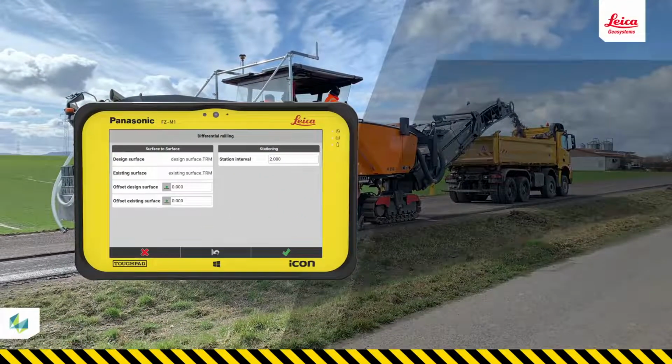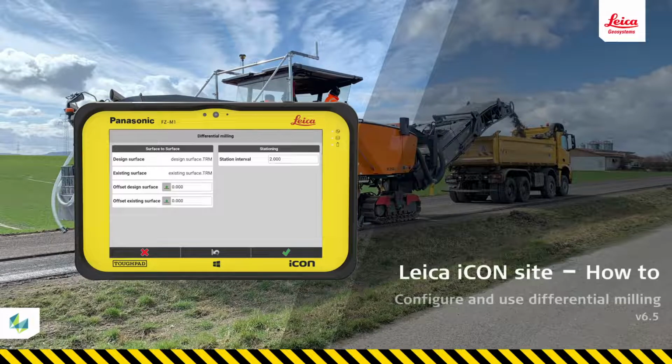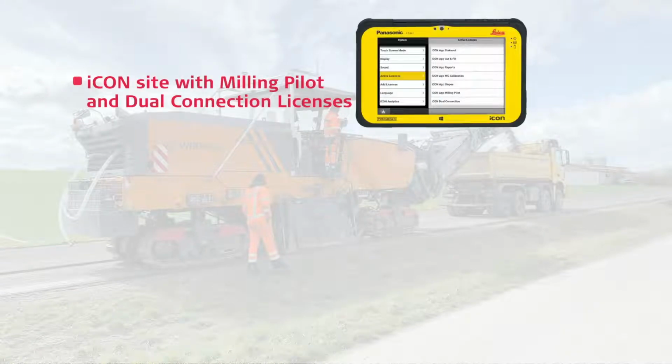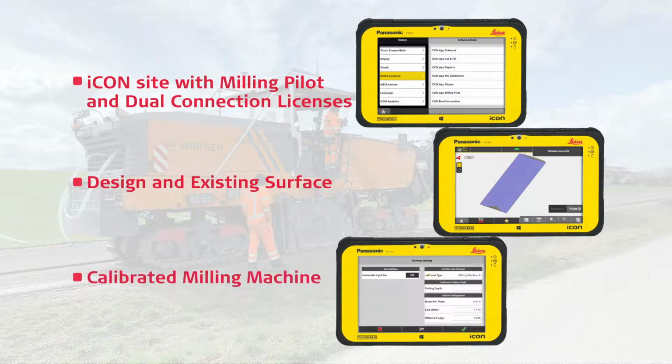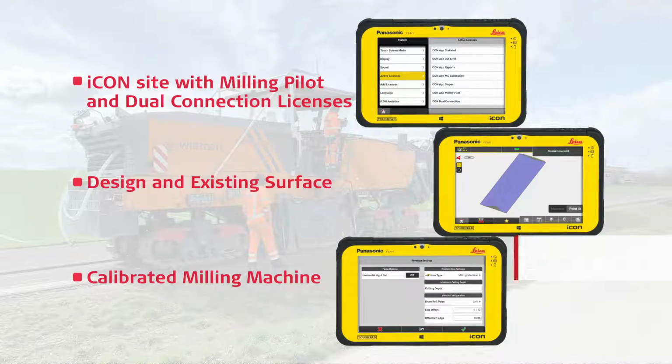Hi, in this video you will learn how to use the iCON site Milling Pilot in automatic mode to renovate a defective pavement. For this workflow we need iCON site with licenses for milling and dual connection, a designed surface and an existing surface, and a calibrated milling machine. You may want to see the video how to calibrate a milling machine.